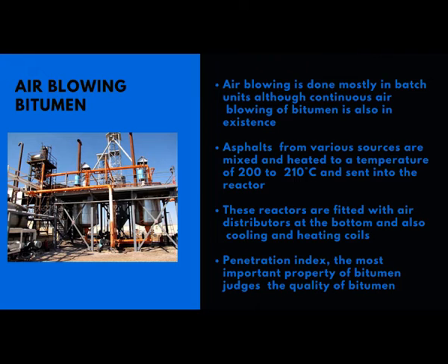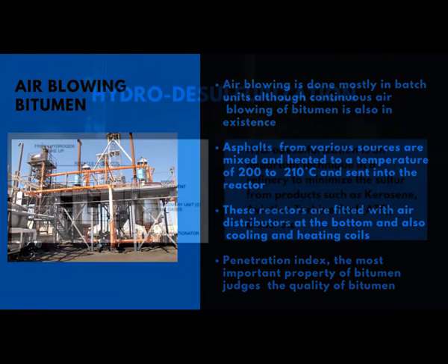For your civic road construction, you require a bitumen of a specific penetration index, while for an airport runway, the penetration index will be totally different. Depending on the market requirements and planning requirements, the operating conditions would be varied, and accordingly the blending will happen, and finally you produce different grades of bitumen in a refinery.